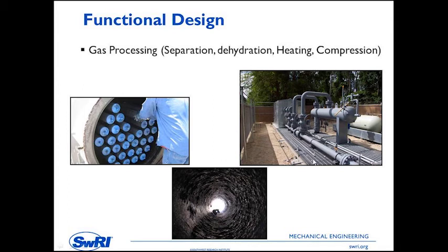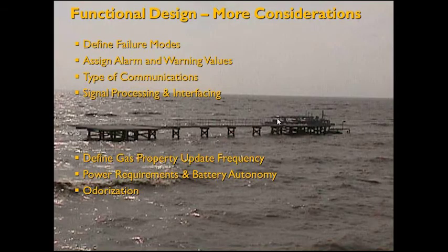Another important consideration for meter stations is what do you do for gas processing? In particular, filtration and separation is an important concern. Over here on the left is a picture of a person changing filter separators in a mainline filter separator. Here's an installation of a city gate with a small filter separator. In fact, this was a turbine meter housed in this house. And here's an odorization assembly that's a part of that meter setting.